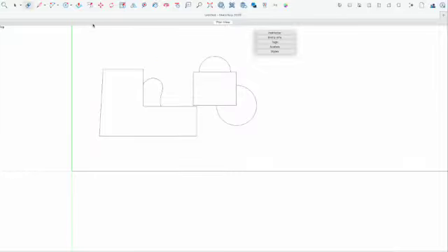One more tool to check out this time, and that is the Move tool. It looks like a little four-point arrow. If I click the tool and then choose one of the corners of my rectangle, I can move it, but it stays attached to the two other points it's connected to. This is called stickiness, and it can be useful in some circumstances, but we mostly try to avoid it. So I'll be showing you how to do that soon too.